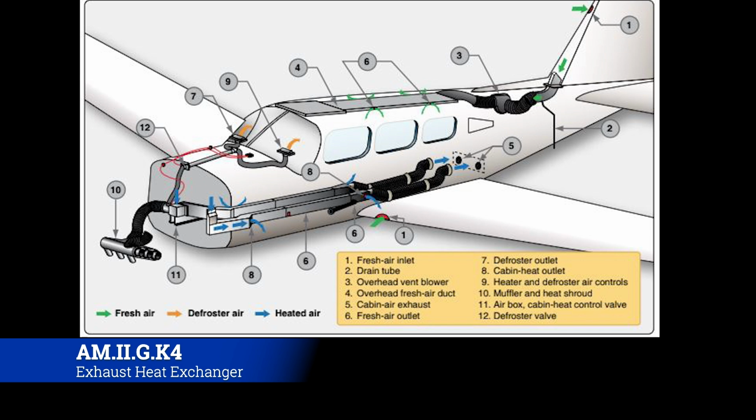But generally speaking, you want air flowing through the cabin if at all possible. And you even do that with pressurized aircraft. The difference is that you have an outflow valve, and the air that's coming in is super high pressure, and the outflow valve just opens and closes to help keep the pressure where it needs to be. Either way, that's how the air flows through the cabin.